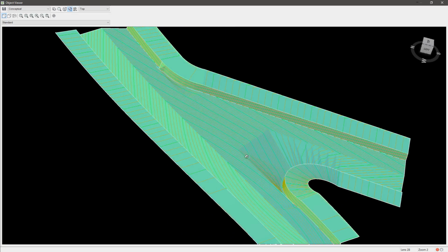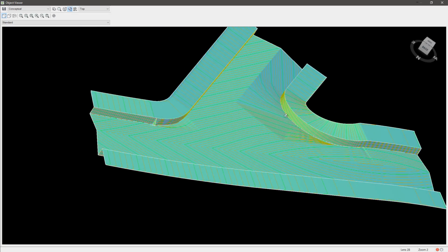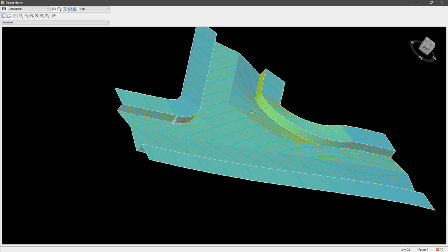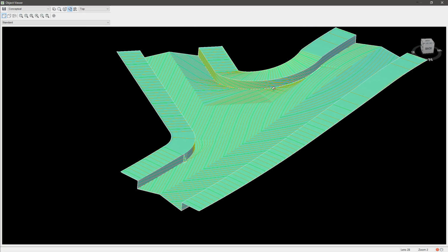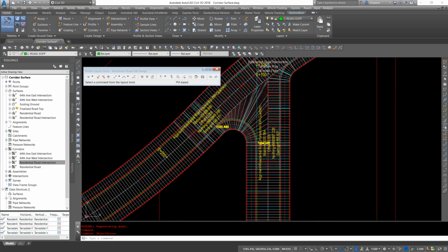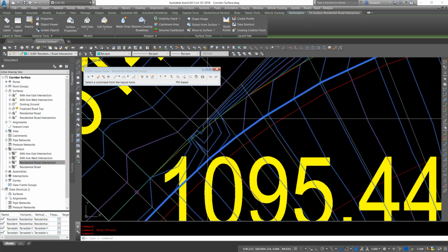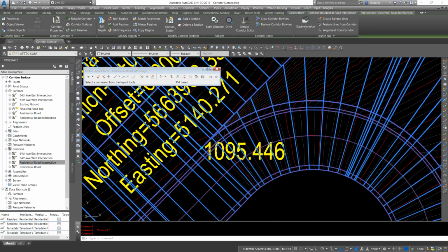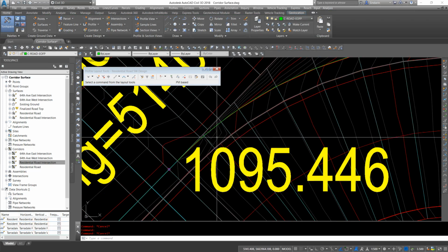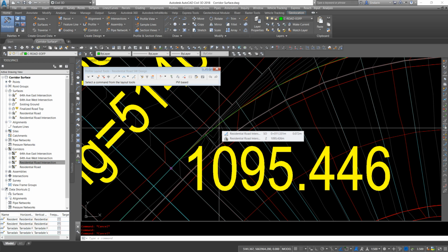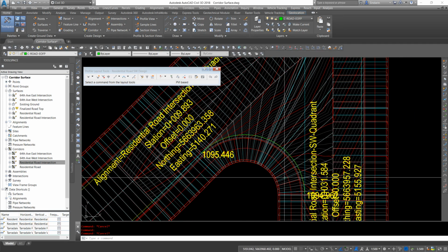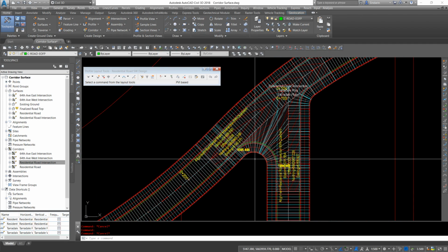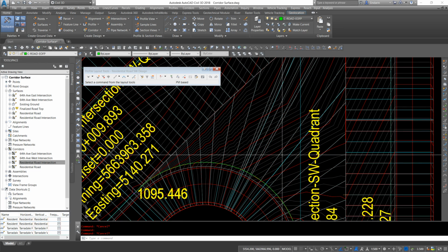So that final step, and again, it's made our intersection a little odd in here, but we could go and fix that a little bit more, smooth it out. And it looks like in here we're having some more contour related issues, but this is a 0.01 contour interval, so it's not a huge deal here. We're just trying to extract the road, and I'm guessing it's just the angle that causes the problems that we're experiencing.